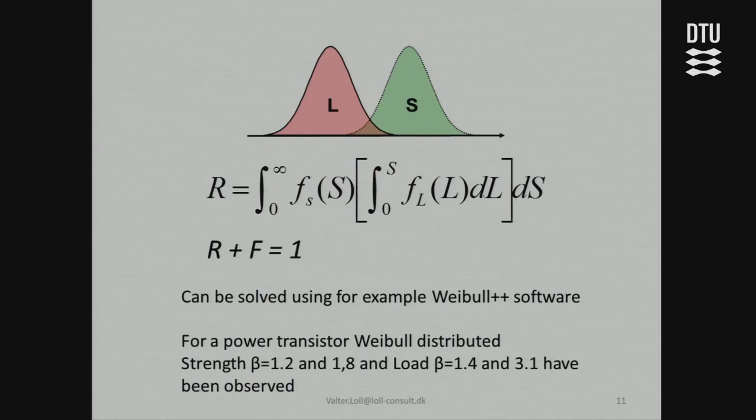But if the designer places himself right here, you will have a failure-free design. And here are some of these curves from A.D.S. Carter. You can see that it depends on the safety margin and the loading roughness, and whether you have a single load or several loads.